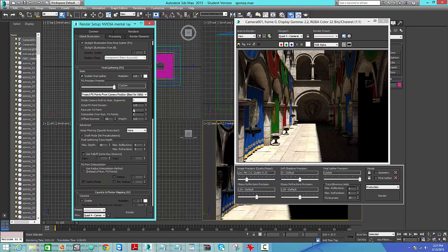As far as point density is concerned, it's a multiplier that makes the points larger so they overlap each other. When they overlap, the rays are shot out like a Venn diagram. So you have one point and then one point that overlaps. When the rays are shot out, they stop gaps from happening, where you'd have a noise gap where the circles hit. So you'd have two light spots and then a black spot. If the point density is large enough, the circles overlap and then the rays overlap each other, and you don't get gaps in lighting.